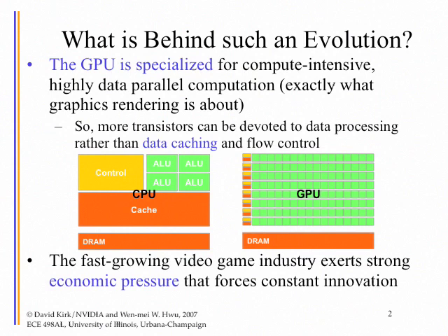The CPU will rearrange instructions, because some of these memory accesses will take 5 or 12 cycles to complete, while it looks at some future instructions and sees if they can do some busy work while waiting for that 5 or 12 cycle latency. All this design costs transistors. That's why on a comparable chip you will see a small number of CPU cores, because each CPU core requires all this logic.